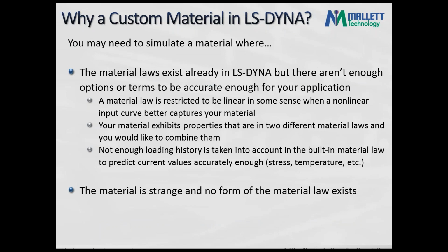material laws may exist in LS-Dyna already, but there's just a little something for your application that you need, to improve the accuracy or to make the behavior of the material exactly the way that you observe it to be. Sometimes the material laws are restricted to be linear in some sense, when a nonlinear curve might be better. You might see your material exhibit things that happen in two separate materials in LS-Dyna, and you might want to combine them into one effect. And sometimes the material built into LS-Dyna doesn't take enough loading history into account to accurately predict certain values: stress, temperature, whatever.